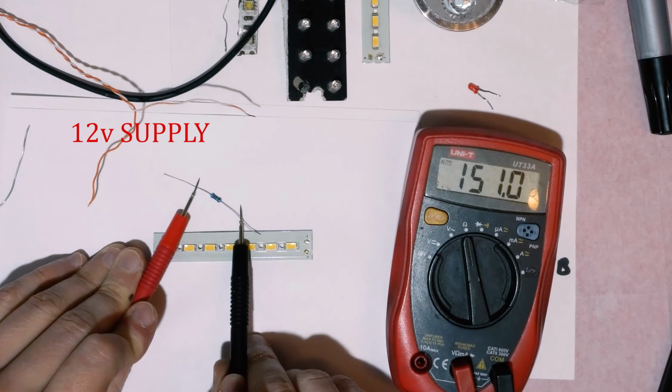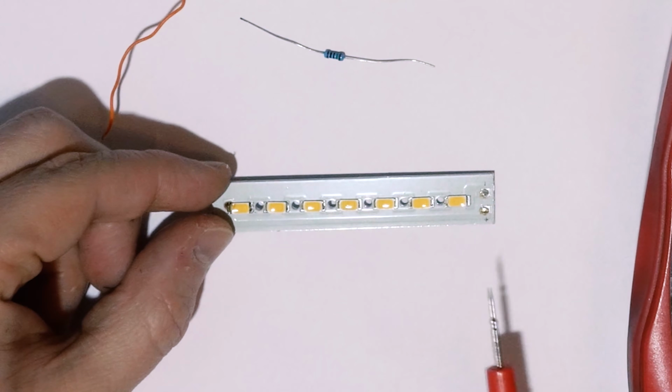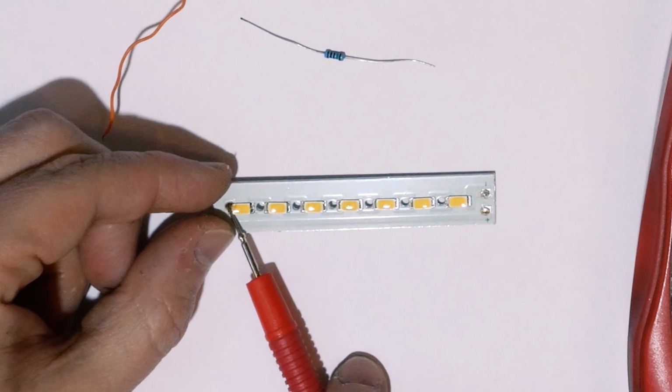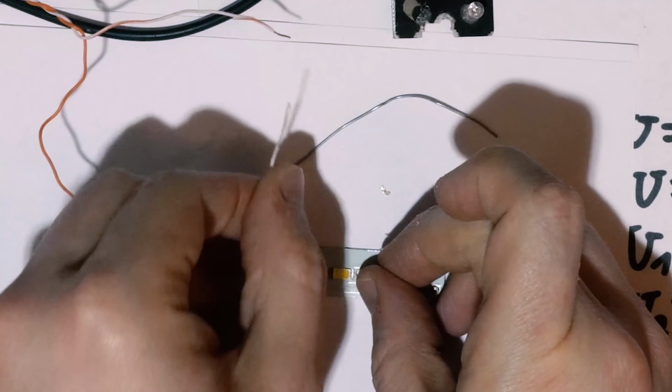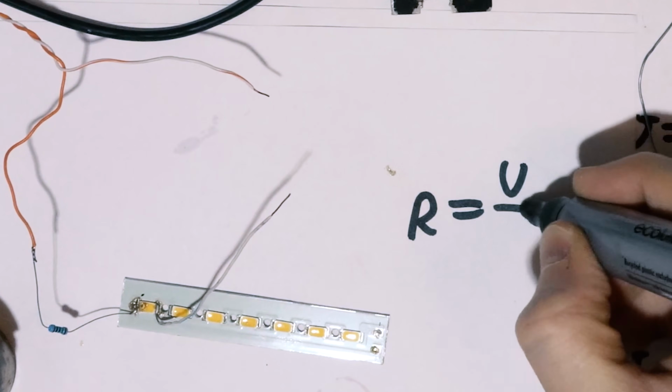By the way, it's always a good idea to recheck the resistor, because sometimes they end up in wrong bags. If we look at this PCB carefully, we can see this wire goes to this pad, which means it's the positive terminal. I soldered an extra wire here, so we can use our multimeter to measure current.